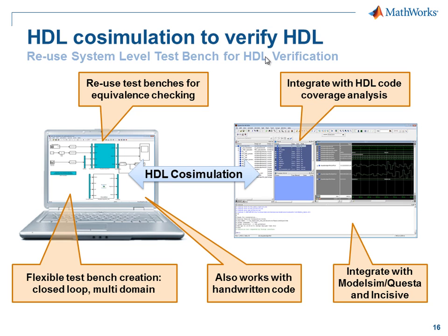So if the test bench itself has a closed loop, which is not a problem. If the test bench itself has multi-domain components, so I might have analog components, that can easily be simulated by using HDL co-simulation. Obviously this also works with handwritten code, and ultimately this allows me to integrate with ModelSim or QuestaSim or Cadence Incisive.